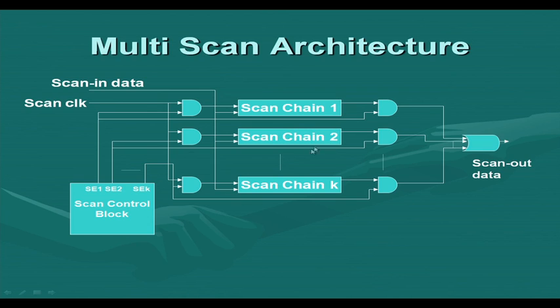And for the scan out purpose, of course, I have to do it serially. So this AND gate has to be enabled. As a result, this chain output will come, or this will come, or that will come. Of course, there are many other components that can be there, like scan chain masking and all that, but that is not shown here.